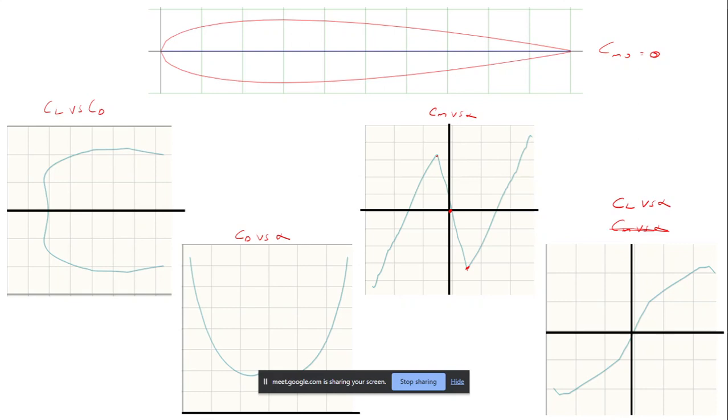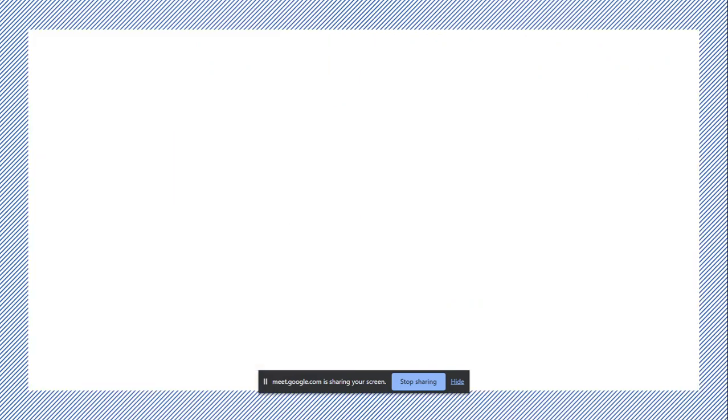Okay, now let's go back and try doing another aerodynamic center calculation, because again I thought there was some difficulty in solving it. So let's take a relatively simple problem this time. Last time it was tapering about the quarter chord. There was tapering on either side. This time let's take something that tapers about the trailing edge. Okay, so it should be easier this time.